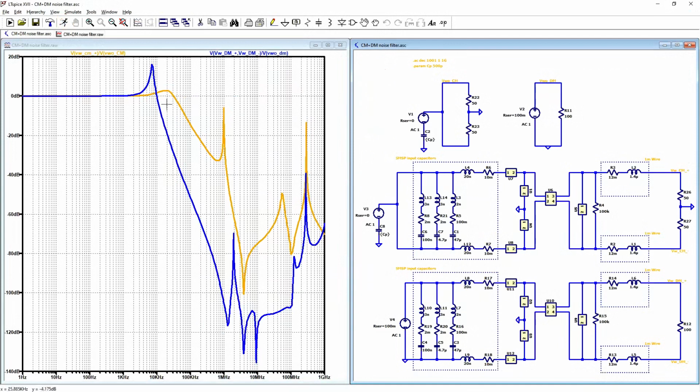You can see that our common mode part of the graph is influenced by the additional inductance in the equations, and our differential mode is also influenced because we have these two CY capacitors, and we connected our one differential mode line and second differential mode line by two capacitors in series.